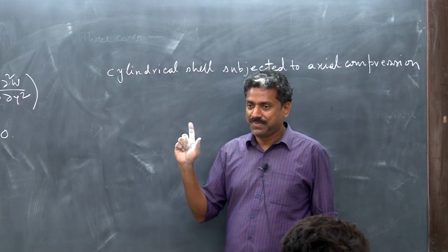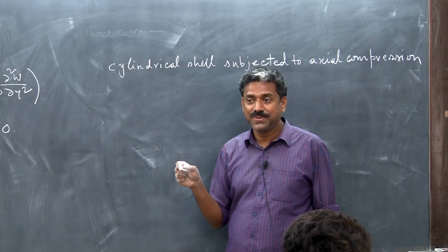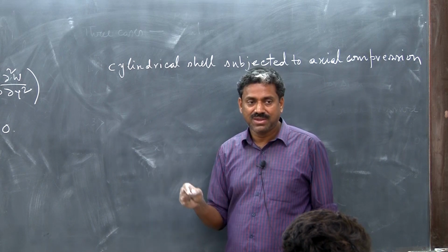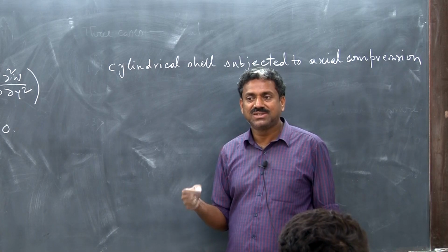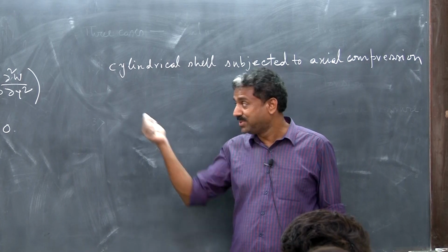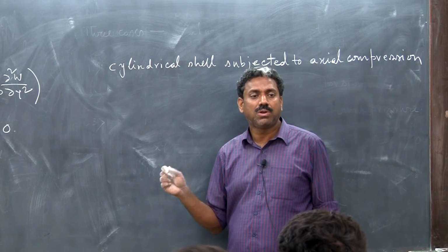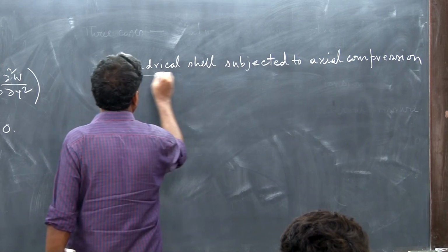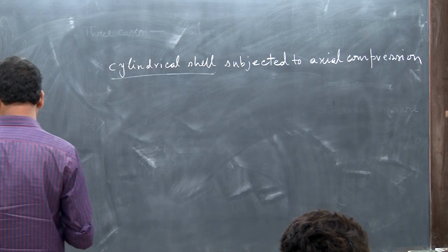assuming an axisymmetric buckling mode, where the bending can be represented by studying the bending of a strip, essentially one-way bending, and we established this analogy with the beam on elastic foundation. So this is another way. You see that increasingly we are imposing more and more complexity. So when we put this in, how will the equations look?